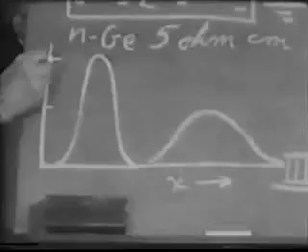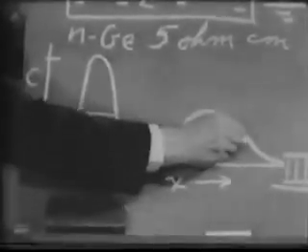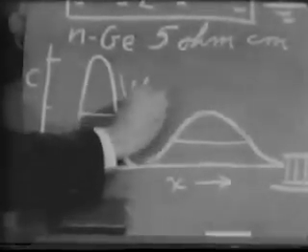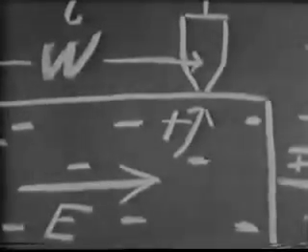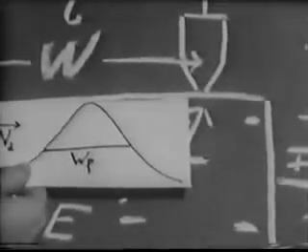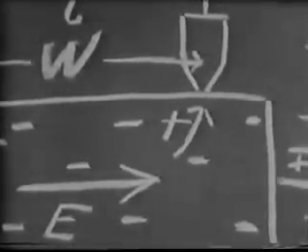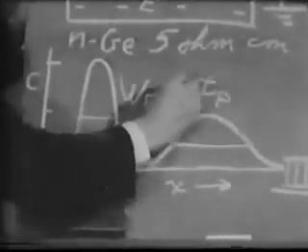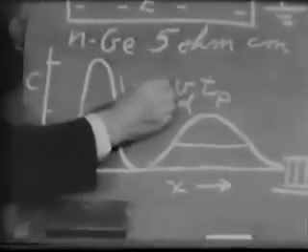Now for our case, consider the width of the pulse at half maximum hole concentration. This width, W sub p, we obtain only indirectly by measuring the time interval that this width, W sub p, takes to pass under the detector at speed V sub d, so that the time interval T sub p times V sub d equals the width W sub p.